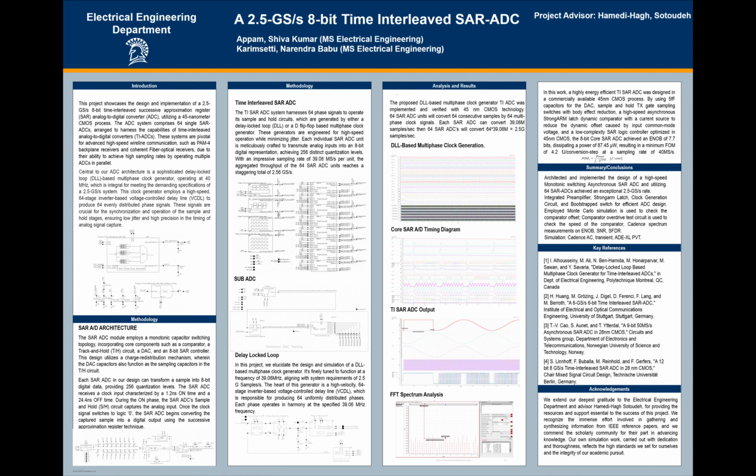So it's a self-sufficient chip. These are the results of the DLL multiphase clock generator, this is the timing diagram of the single core ADC, and this is the overall output of the time interleaved SAR ADC. And this is the FFT spectrum, after the DAC, of the single core ADC.